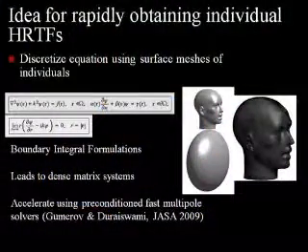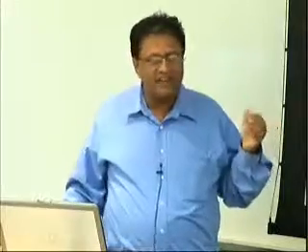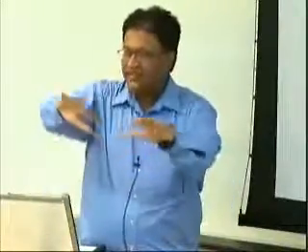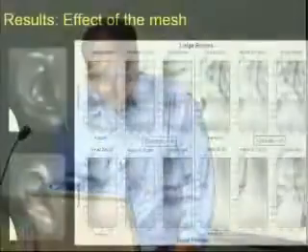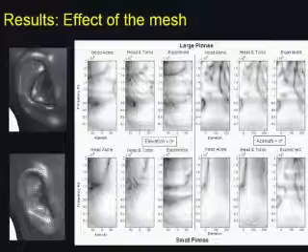We also do computation of head-related transfer function, computation of scattering. So now we are developing arrays which are not necessarily spherical in shape, but say head-shaped or other shapes. Suppose I put microphones on some arbitrary scattering object like a robot, a network of microphones. How can I beamform with those microphones? Then I would have to solve the wave equation to get those beamformer weights, and we're working on those. But we're going in too many different directions, so I think I'll just take this opportunity and conclude, and thank you all for inviting me here.